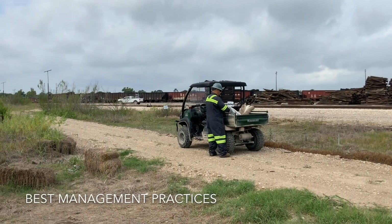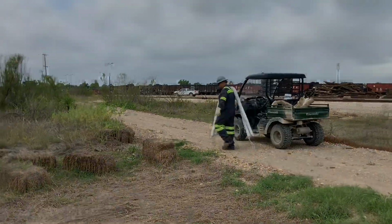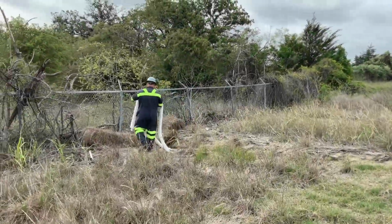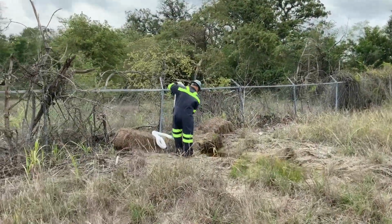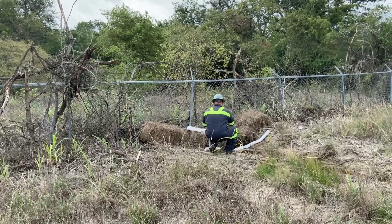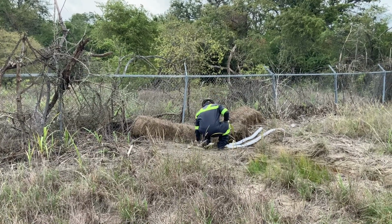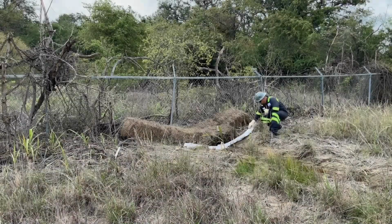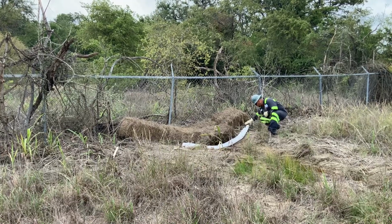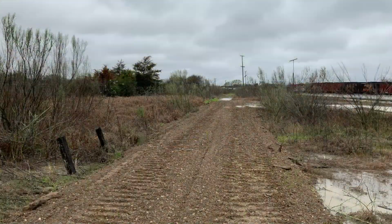Best management practices for stormwater pollution prevention include, but are not limited to, maintaining storage yards and roadways to minimize the generation of dust, planting and maintaining vegetation to filter and reduce suspended solids, cleaning up drippage and spills when discovered, diverting stormwater around storage areas, installing silt fencing to control sediment, and utilizing and maintaining pollution prevention socks in ditches and outfalls.